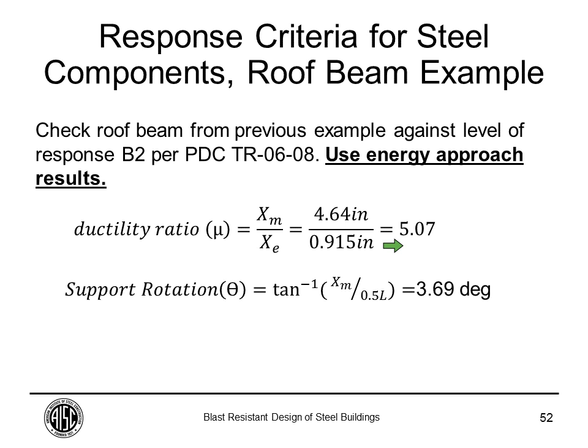And then, based on the span, we used half of it. It was a 12-feet span, and then we used the inverse tangent of the maximum deflection divided by half of the span, and we calculate a support rotation of about 3.7 degrees.